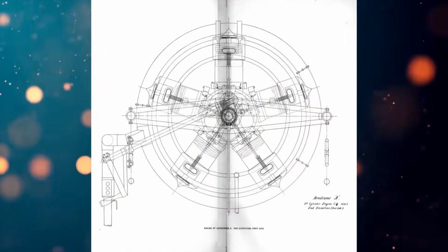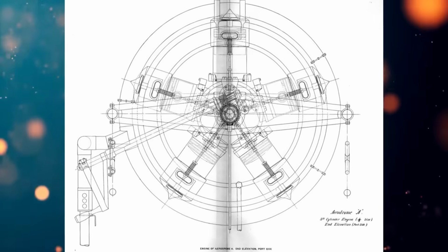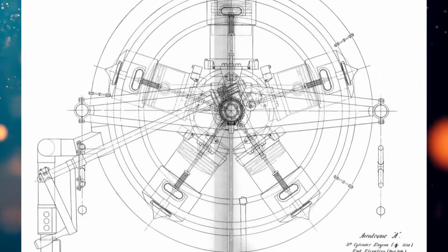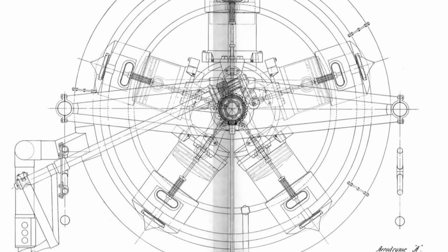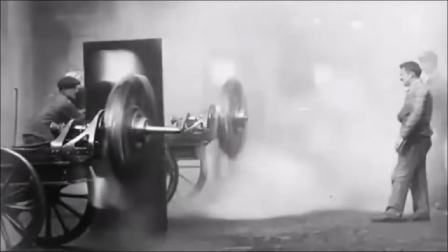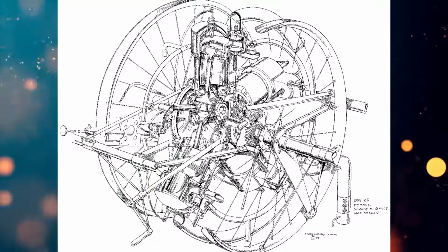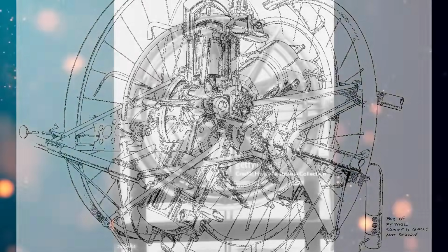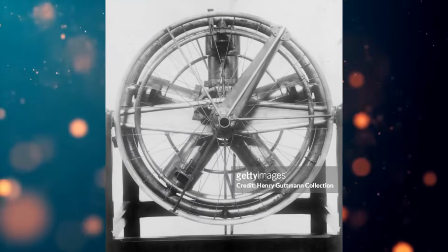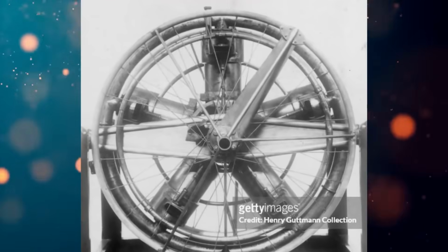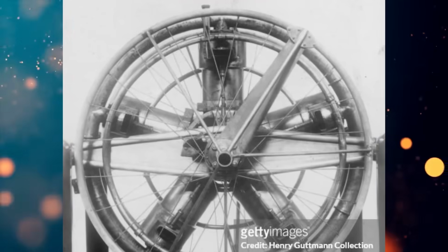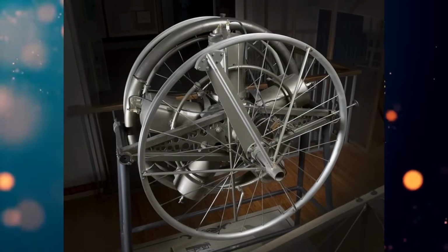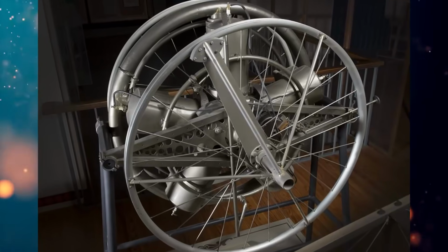The engine was completed fairly quickly, but it turned out to be not powerful enough, about 8 to 10 horsepower. Charles expected a power output of around 12. The new engine had cooling problems. The rotary engine, thanks to its self-rotation, didn't even require fins, but the stationary cylinders overheated quickly. Manley solved the problem by equipping the engine with water cooling. Soon, the unit was producing 12 to 16 horsepower. Encouraged by his success, he increased the displacement of his 5-cylinder creation and brought the power up to 52 horsepower. It was the most powerful lightweight engine at that time.